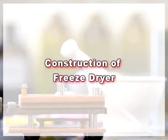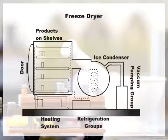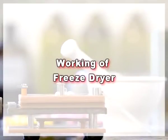Now come to the construction of the freeze dryer. A freeze dryer consists of a drying chamber in which trays are locked, heat supply in the form of radiation sources or heating coils, vapor condensation and absorption system, and a vacuum pump and steam ejector, or both are there. The working of the freeze dryer is in the following steps.